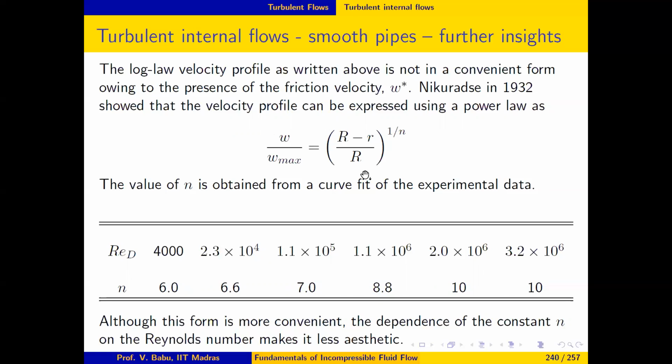And the other thing that emerges from this is that it is quite clear where the profile for turbulent boundary layer, namely u over u infinity equal to y over delta raised to the 1 over 7, came from. So it's clear that the power law profile that is widely used for turbulent boundary layers over a flat plate, the 1/7 profile, it's clear where the profile came from. And it is valid up to Reynolds number of about 10 raised to 5 or so.